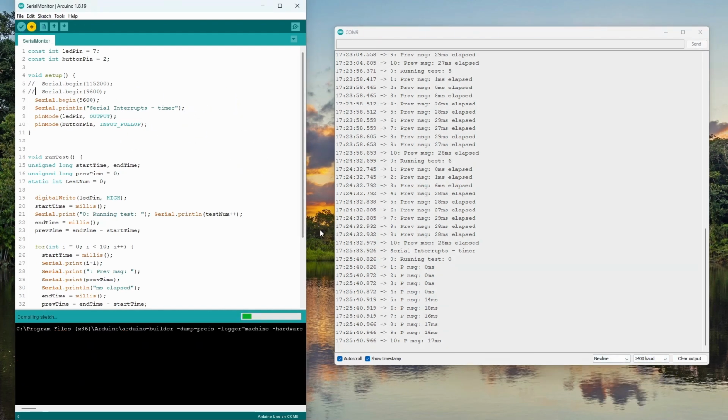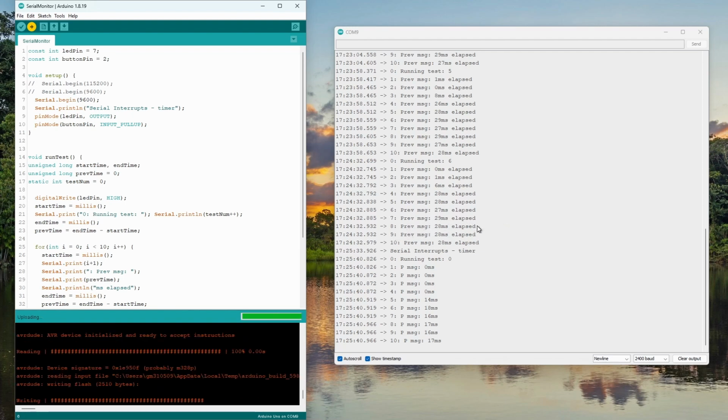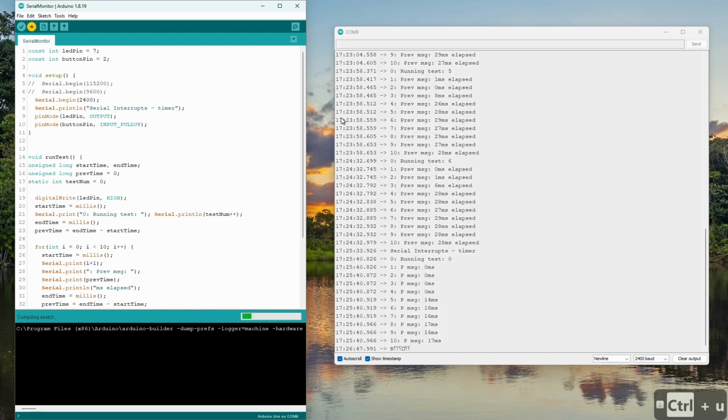Now the reason I'm going to drop the speed is because I want to show that at the lower speed it takes much longer for these messages to come out, and in fact it'll take 4 times as long. So where this one came out in say 32, so what's that, about 200 milliseconds, this should take almost a full second. If I'm going to drop the speed, I actually have to change the number as well, not just copy and paste the line.